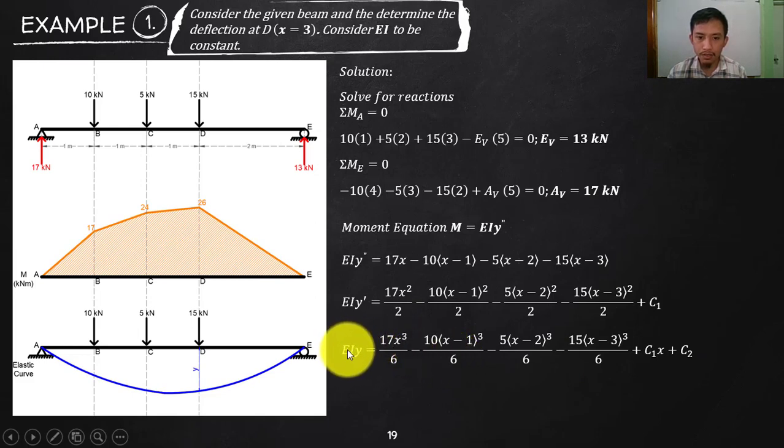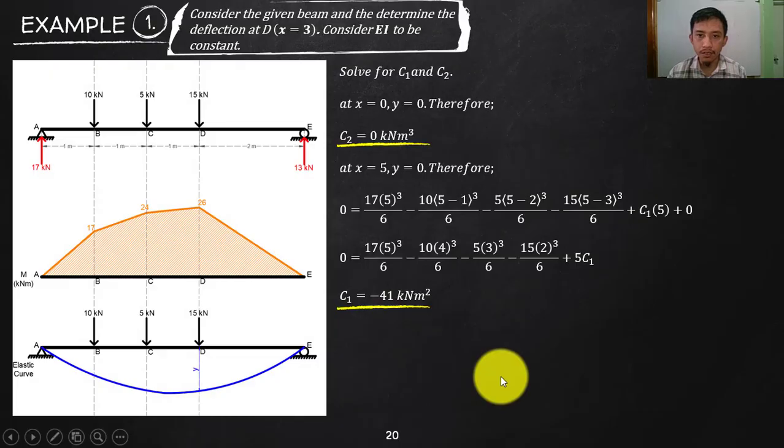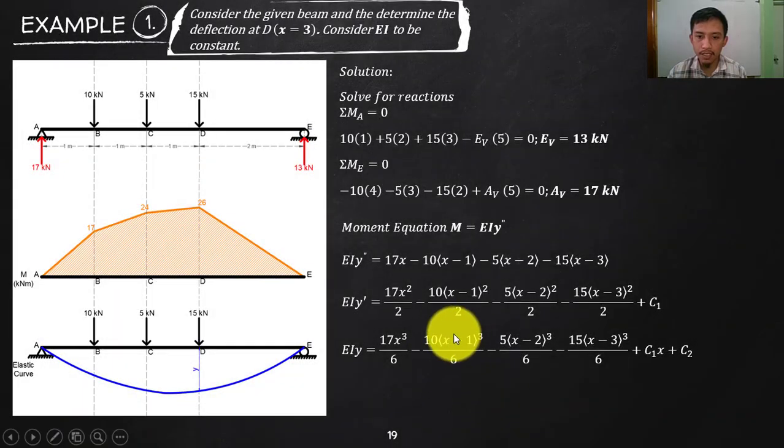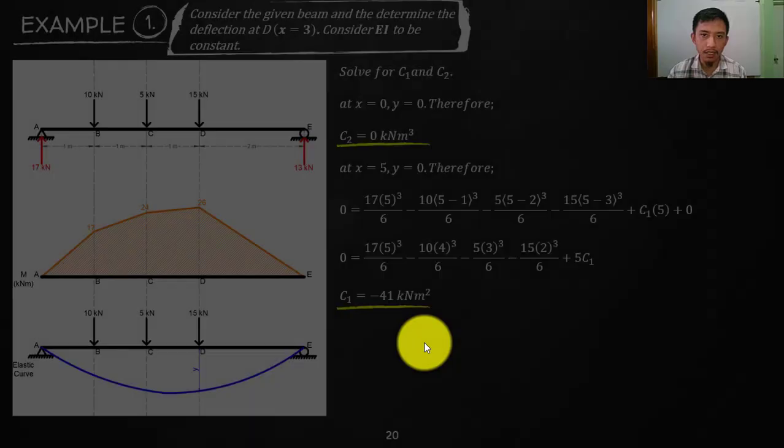So if you want, all you need to do is cross multiply EI in this complicated part here, then you will have the equation of your deflection with respect to the distance x. However, again, do not forget the purpose of your pointed bracket. We need to screen the terms due to that pointed bracket. The inside of that should always be positive. If that is negative, then we can just make that one 0 so that it will make your entire term 0. That is the restriction of your pointed bracket.